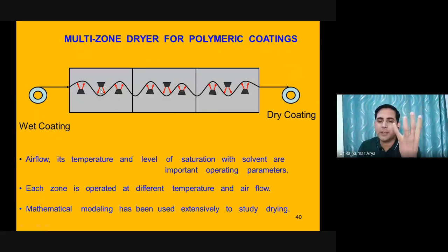When we have high moisture in the beginning, you can give high temperature and high airflow rate because it helps you take out the maximum amount of moisture. Later on, you have to control your temperature and airflow rate, because the same amount of heating or energy cannot be supplied, as it will burn your product or change your product quality.